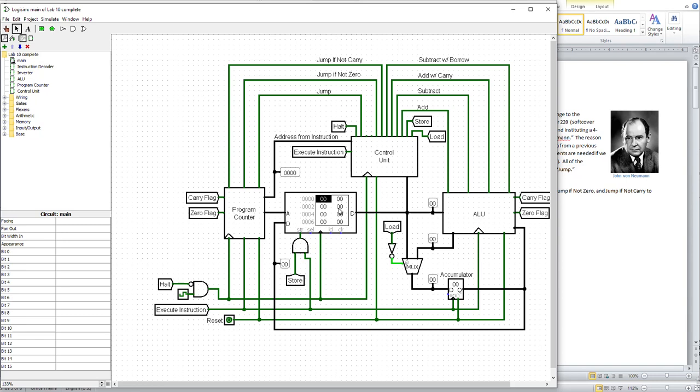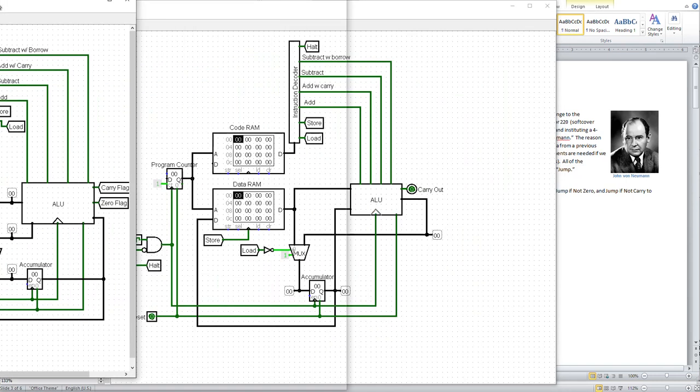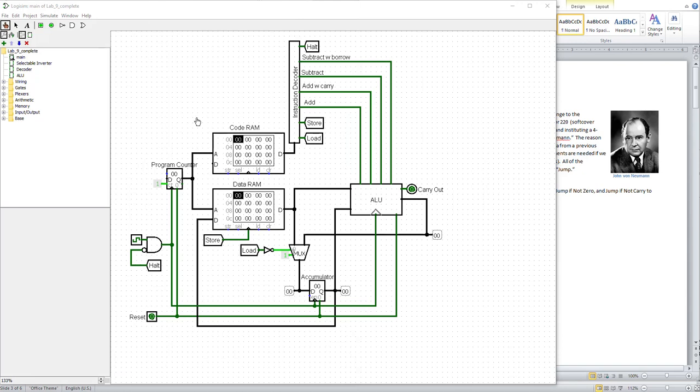So the drawback is it takes longer to execute, but one of the benefits is it's a little bit more efficient in resources because now you only have one RAM array instead of 2. Having said that, this Harvard architecture is something that's implemented even today in microcontrollers like you'll see in the ATmega for the Arduino, or the microcontrollers that you have in your car, your toaster, your washing machine, your laundry machine. So it's possible to make a fully functional computer. The only difference between a microcontroller and a computer is file storage and an input-output system with a Harvard architecture.